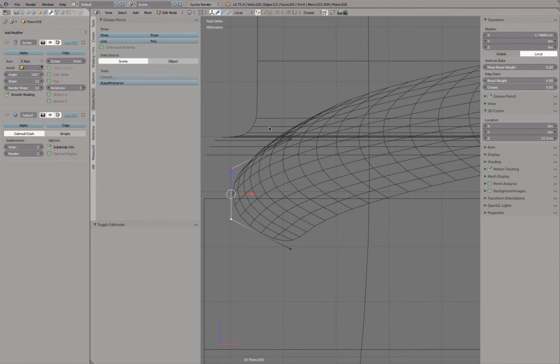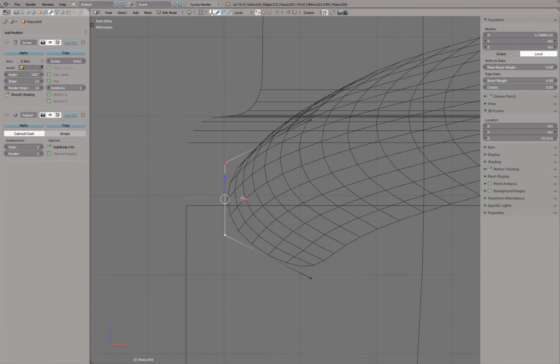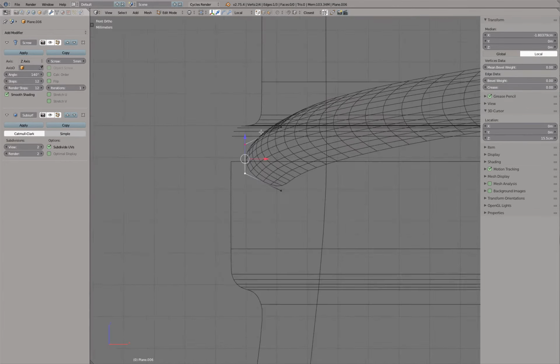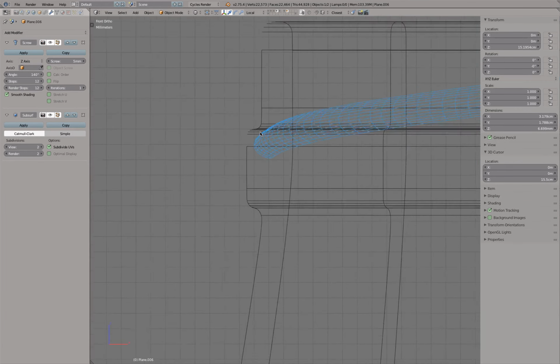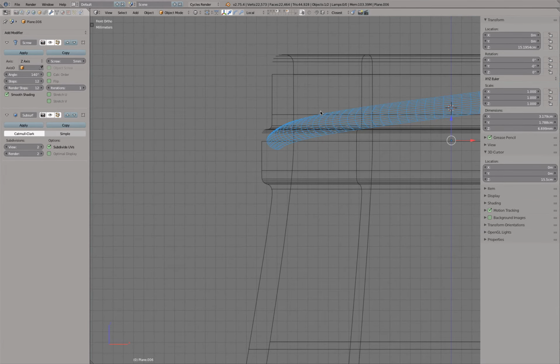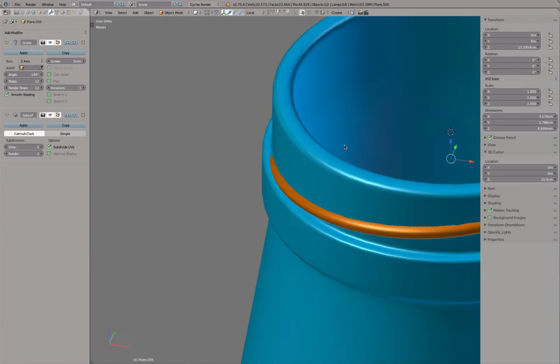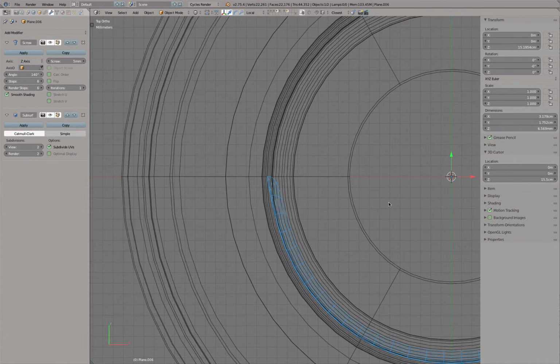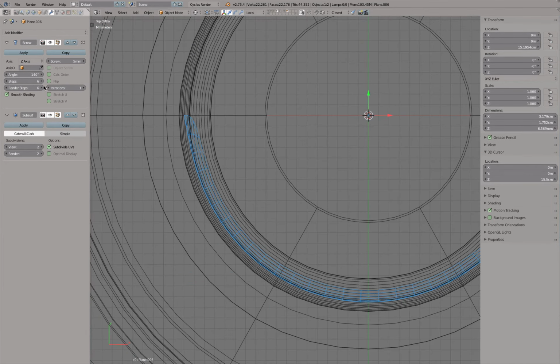To exit this command, press Escape, T, and for example, we could pull this one out a little bit there. So now the threading has more the kind of like the depth of 5mm when it comes out of the glass bottle. But 12 steps is actually a lot. So what about 6? I'm trying to simplify it. And you notice what happens when I simplify it with fewer steps. We are losing our width a little bit. So maybe 10.